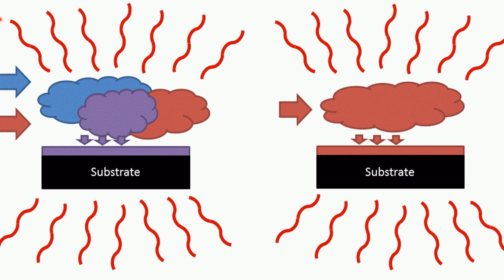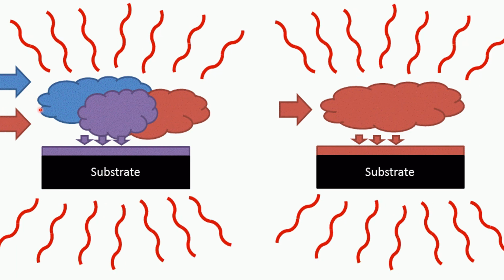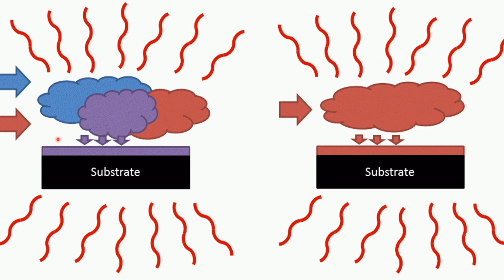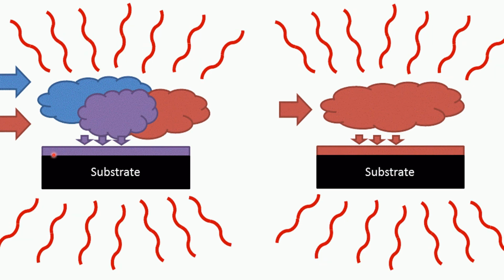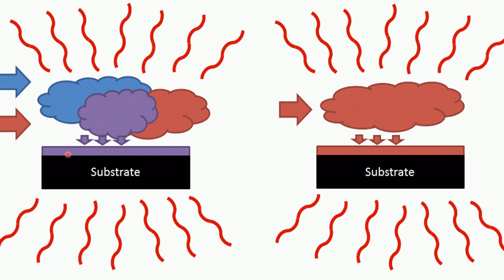Usually the precursor material is introduced in a reaction chamber by carrier gases, and when the precursor material reaches the surface of this substrate, the precursor material, which is in the form of a gas molecule, reacts on the surface of the substrate, and at the end of the day it gets condensed and converted into a thin film.